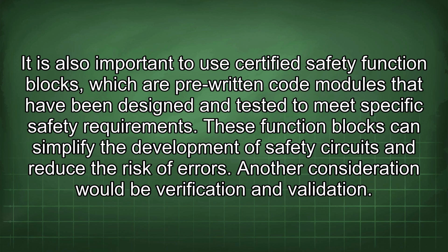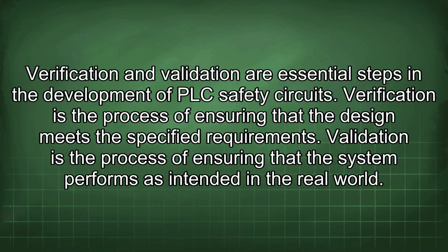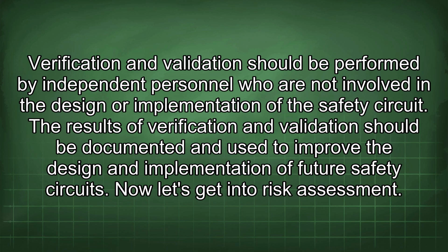Another consideration would be verification and validation. Verification and validation are essential steps in the development of PLC safety circuits. Verification is the process of ensuring that the design meets the specified requirements. Validation is the process of ensuring that the system performs as intended in the real world. Verification and validation should be performed by independent personnel who are not involved in the design or implementation of the safety circuit. The results of verification and validation should be documented and used to improve the design and implementation of future safety circuits. Now let's get into risk assessment.